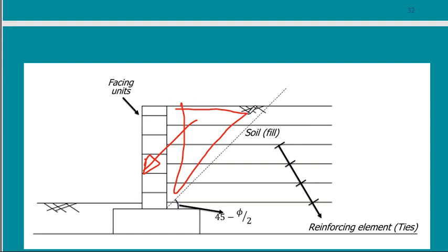If my facings stopped here, suppose that I just use these lines. What will happen? Of course, this line will make this as one part, but it will fall as one part. Instead of falling as pieces or dumped below my embankment here, it will just fall as one triangular piece.